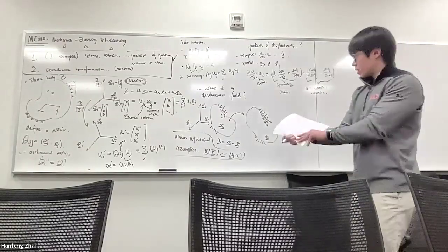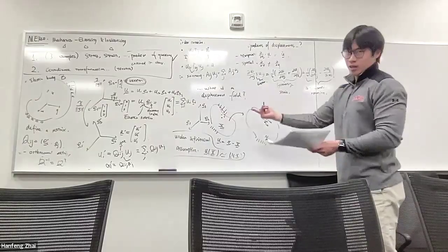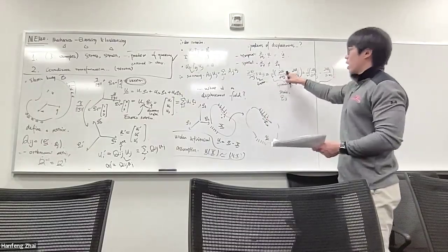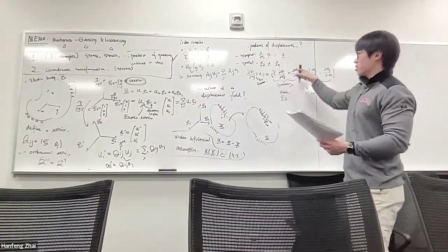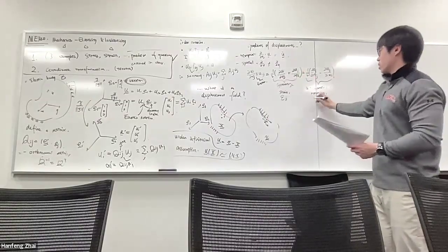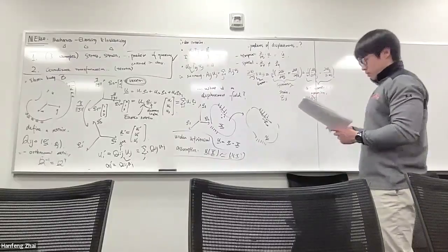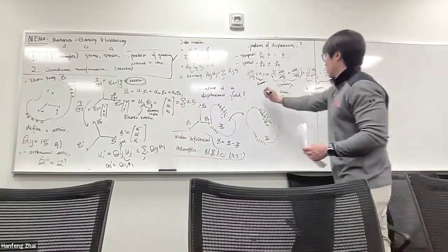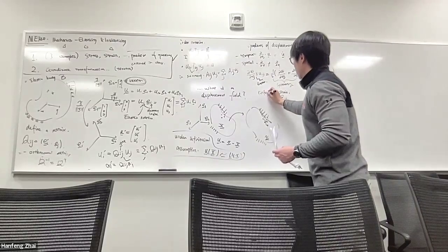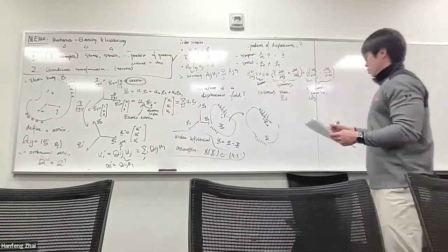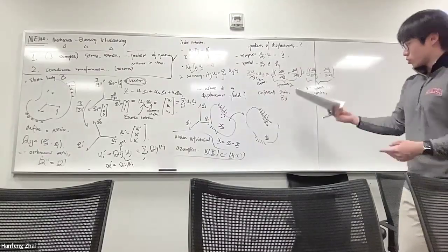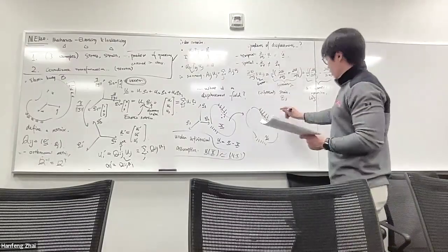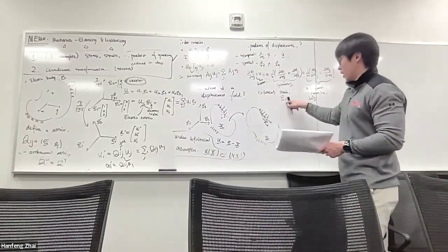To be precise, we can define different Greek letters. We define strain as epsilon. This epsilon ij by definition is 1/2 (ui comma j plus uj comma i), and it's been symmetrized. The antisymmetric gradient, we can use omega. This is the infinitesimal strain, and this is the infinitesimal rotation. The small strain, small deformation strain. And the strain, we look at it, also has two indices, i and j.